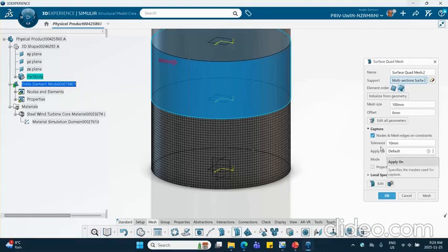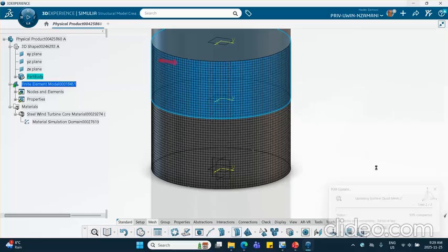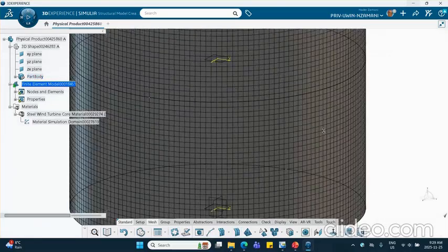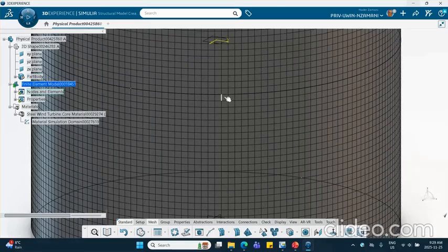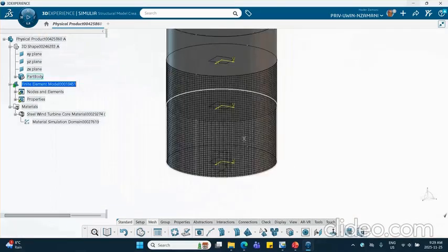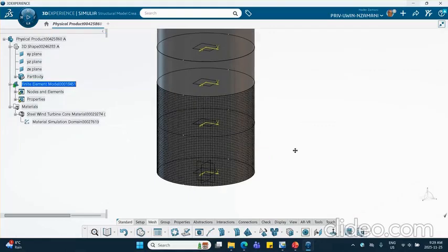These numbers we're not going to change. Now, it is important that we have this thing checked. That's why if it sees any node within 10 millimeter of it, it's going to get merged with that. But everything is okay here. So we say mesh, and then we say okay. Incidentally, at least here it may be obvious, but we're going to check that later on.